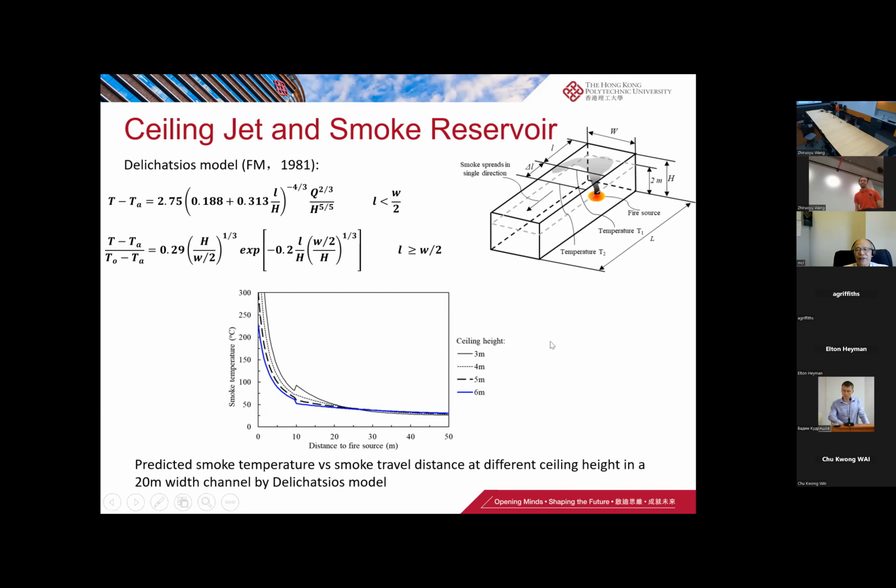And the safety factor is actually for the smoke extraction calculation for the plume models. That's normal practice. When you have a plume model to calculate the smoke production rate, we normally give a safety factor of 1.2. That's practice in Hong Kong, and I think in Australia as well. But in some cases, the authority may ask you to give a factor of 2 for a small fire. That's also fine, because the smoke extraction fan sometimes can be very big with small smoke reservoirs.